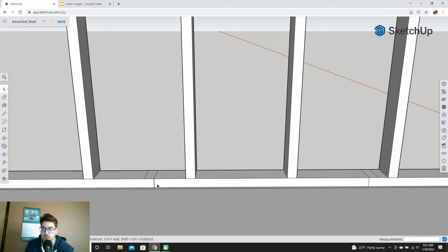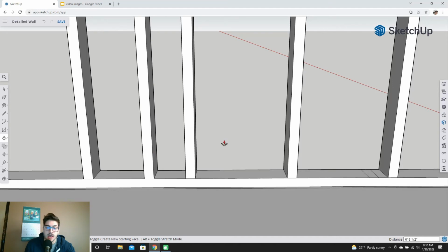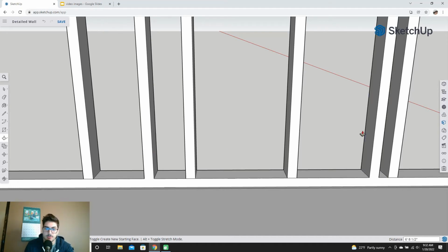And you house people on the internet can check my terminology, but they just go to the height of the door. So if you think about this, the rough opening is supposed to be 82 inches from the ground. It's sitting on a bottom plate that takes 1.5 inches of that. So the height is actually going to be 80.5 inches from the top of your plate. So I'll extrude those real quick at 80.5, and then I'll talk about what we did.